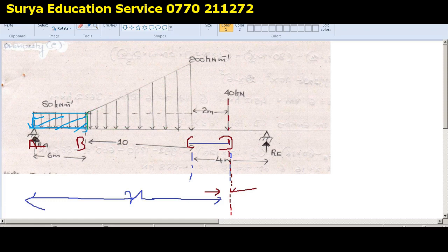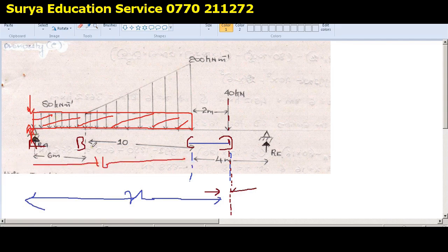And right, so according to this calculation, what I have done is I have considered this entire rectangular portion up to the end. That is also possible, right? Because I have considered this entire rectangular portion. Very easy. This length we know is 80, but in a different unit, and this distance we know is 16. So I have considered this whole rectangle plus this triangle in the calculation, because that is easy. This base, what is this base? 10. The height: this is 200 and up to here it's 80, so the balance is 120, right? That is how I have considered it in the calculation.